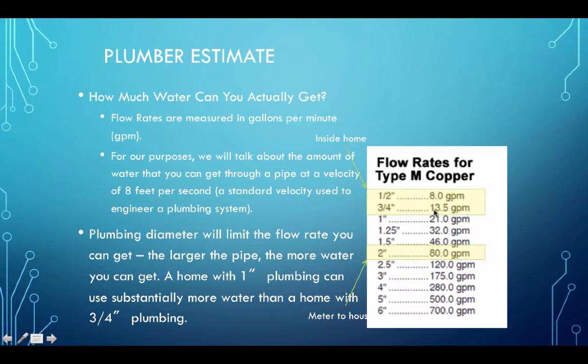And that can carry, at typical residential pressures, about 13 gallons a minute. So my house in Lubbock, I can use 80 gallons a minute. You could use that as a way to get another upper estimate of the amount of water you'd have to supply to a node. You assume that everyone's using the max amount they can use for a short period of time. That helps give you a maximum flow rate.